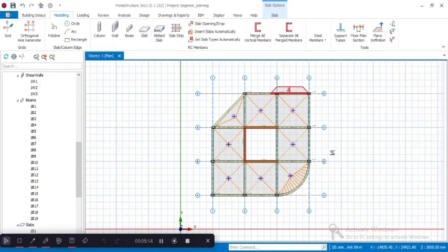So tip, the slab column edge line also includes circle, arc, and rectangle, and the ability to convert to a column or slab hole or slab drop after drawing a closed shape line. Select it, right-click it, convert to column or slab hole drop. So that's another feature that we can use. We're not using it here.